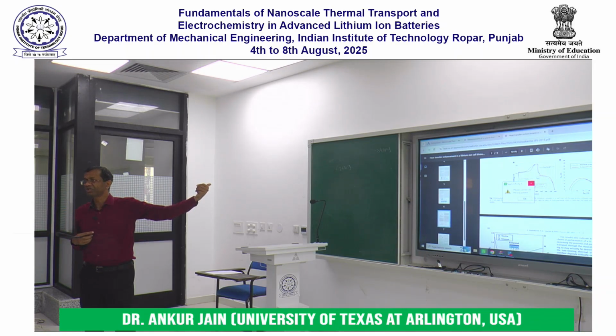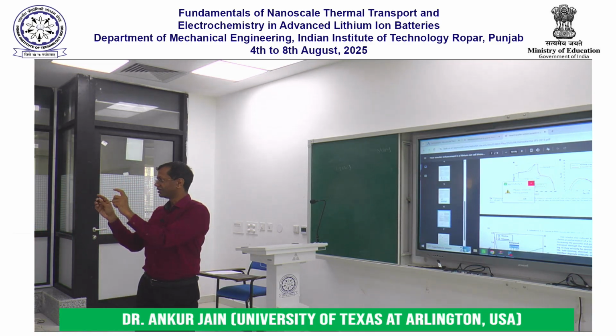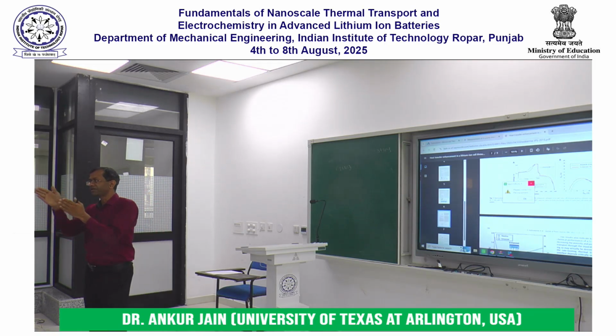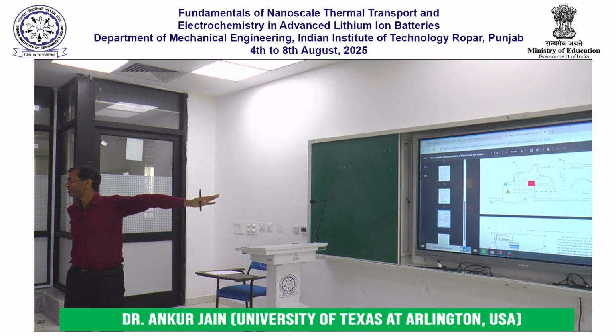We didn't do that in our simulations yesterday, right? We didn't even worry about individual atoms and molecules. We just said, okay, this material has a thermal conductivity of whatever. That number that we assign captures the behavior of atoms and molecules. Atoms and molecules that don't vibrate very fast and don't transfer the vibration very fast have low thermal conductivity. And atoms and molecules that transfer it very effectively have high thermal conductivity. That is how we account for those atoms and molecules in our bulk simulations.